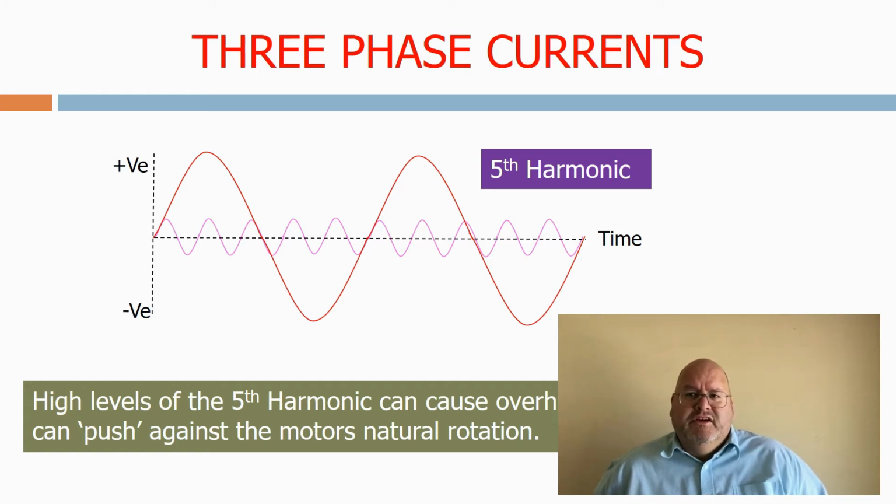Harmonics are an unavoidable feature of an alternating current system that can be useful indications of equipment going faulty, but can also have serious consequences for an electrical utility. I once worked for a client in London who had to replace over 2,000 televisions for customers, all located in the same area. Upon further analysis, it was found that an old power factor compensation unit was causing serious harmonic distortions that caused the damage.